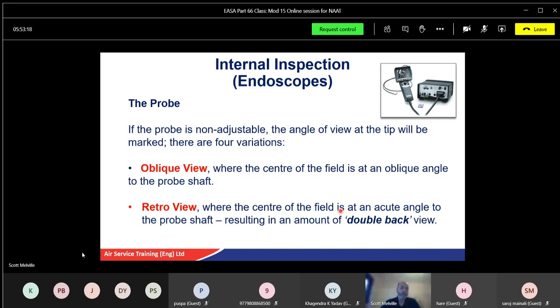And that's the iPlex kit, as we call them. They're the more favourable ones for measurements. Whereas before, it was down to the engineer's eye, and we'd use a blade as a reference. So if we found a problem on a turbine blade, we'd have a spare blade outside, and we could guesstimate the length of the damage or wherever the crack was, just by comparing it to a natural blade.